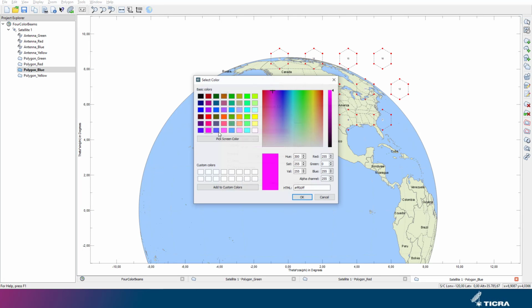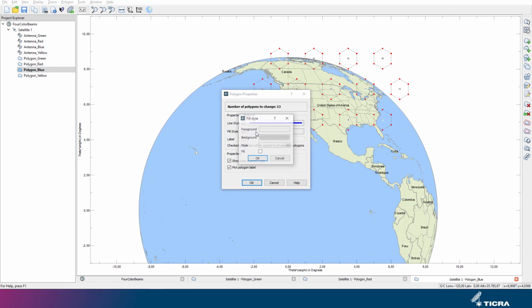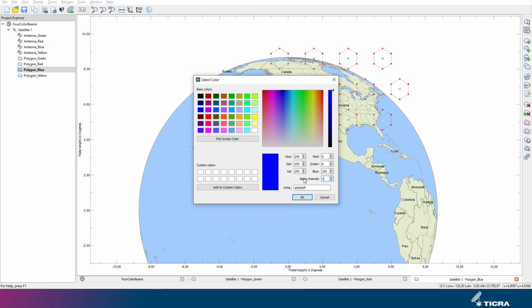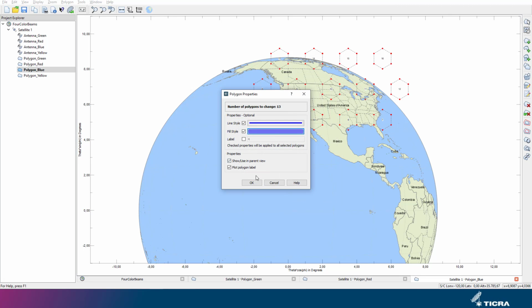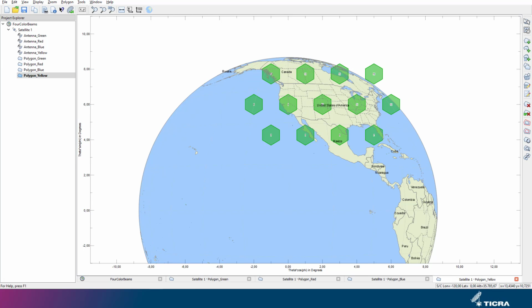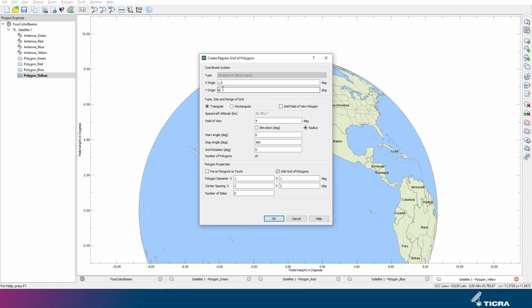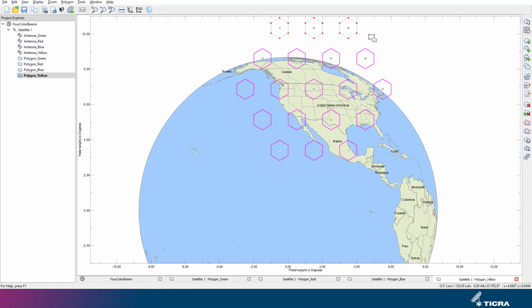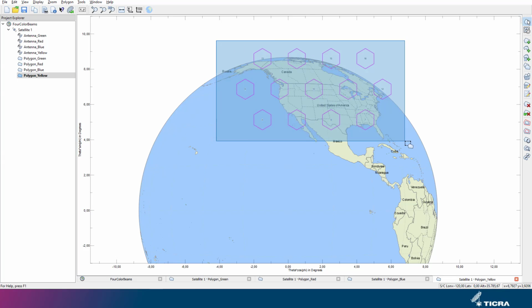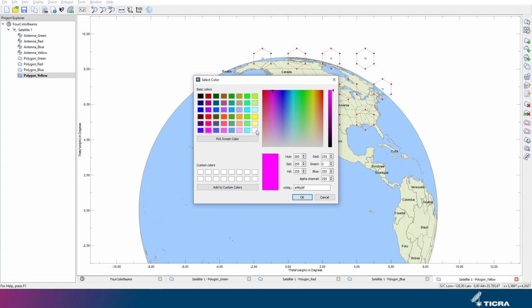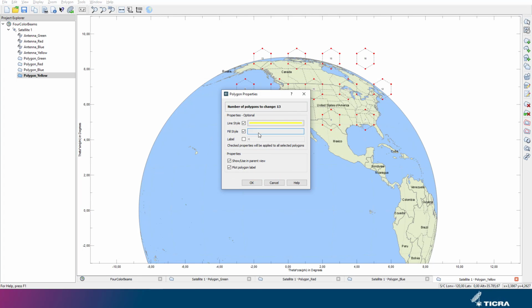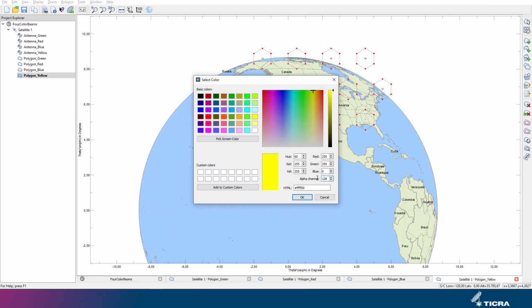The position of the red, blue and yellow beams with respect to the green ones can be obtained by drawing a triangular lattice of the 4 colors, which leads to the numbers that we use for X offset and Y offset here. An illustration of this can be found in the tutorial case in section 15.3 in the SATSOFT manual. We also note that the numbers here scale with the beam size, which in this example is 1 degree.